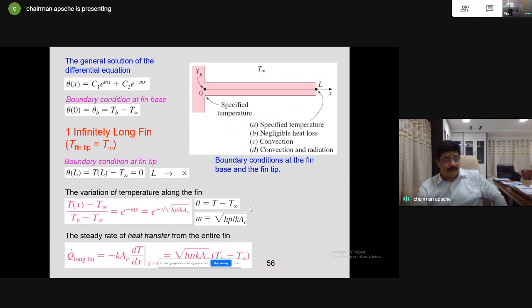But we all know that the Carnot cycle is not a practical cycle. Why? Because you have two reversible adiabatics and two reversible isotherms. An isothermal process needs a very slow process, while a reversible adiabatic needs very fast movement of the piston. So it is not possible for you to have it.